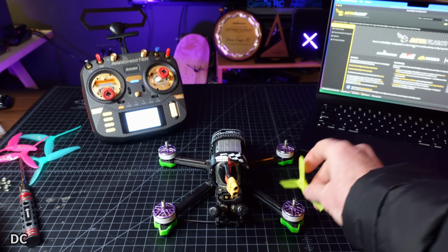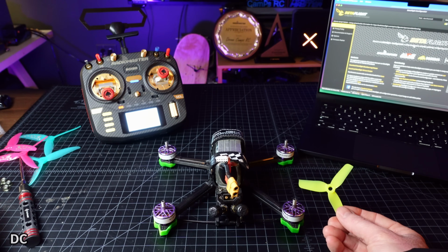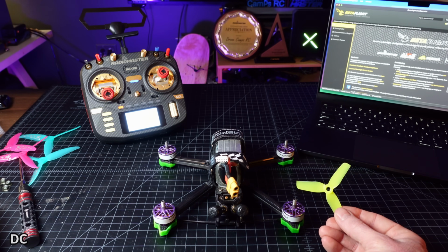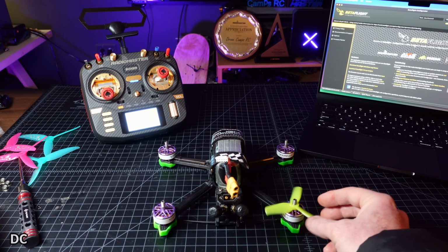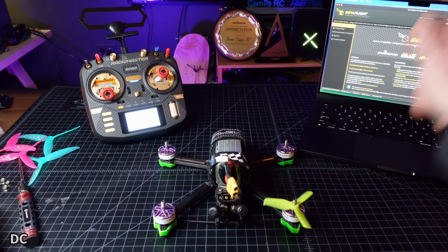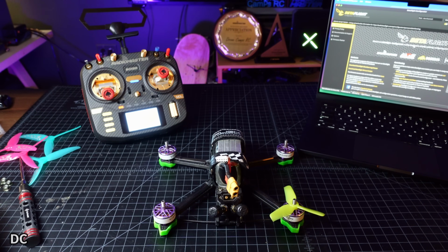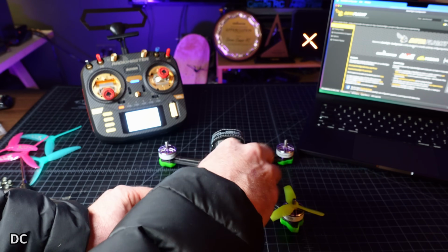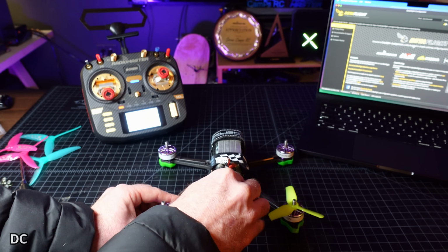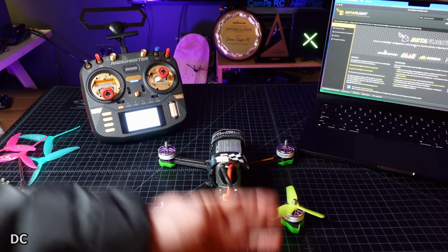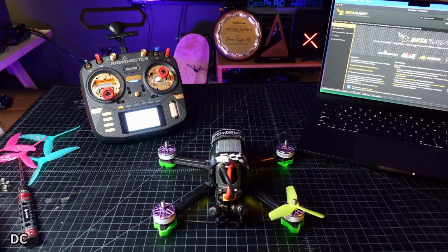And this is the second technique that you can do, is you could take a smaller prop, a little tiny, say 3-inch, if you're working on a 5-inch, obviously, much smaller prop. But I don't put a nut on top of it. I just want to let it free spin. So that way when I plug in the quad and I arm it, it's not going to fly off the bench. The worst that's going to happen is this little guy is going to get airborne, which it has in the past on me. But this is a really easy way to check the direction of that motor.